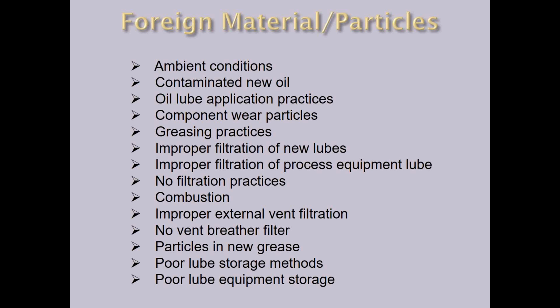I go to plants all the time where there are no filtration practices, where there has to be some filtration of your equipment. Combustion engines produce lots of particles. Improper external vents, we talked about the desiccant breathers, no vent breathers. Particles in new greases. Here's one thing I'll let you know: all new greases, even from the major manufacturers, most of those greases have particles in there because the manufacturers are not filtering the lubricants down to these real low micron levels before they make the grease.